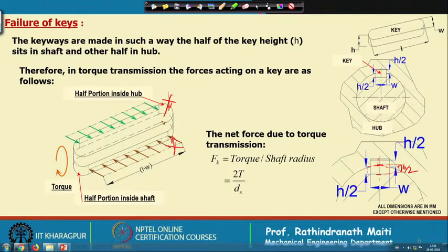This is very important, because if we make the total groove height exactly equal to the key height, in that case if there is some error, then a stress will be here, and due to that some clearance will be generated between the hub and the gear, whatever small it might be. This will be a failure in torque transmission.